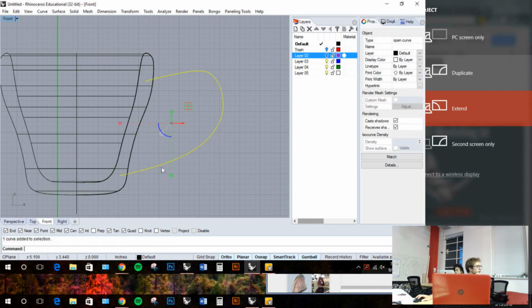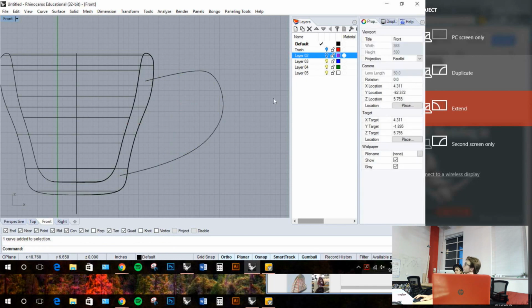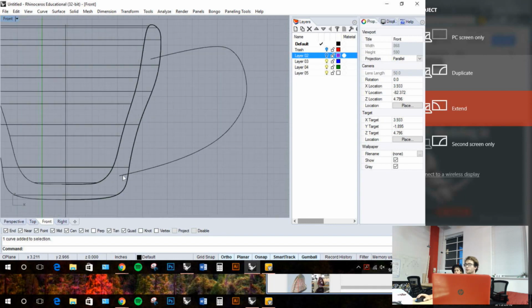Is anybody having trouble with that? Mine's like sticking to each of the edges. Like I can't select. Okay. If it's selecting the edges, hold Alt, or for Mac users, I believe it's hold Command, to disable the object snaps temporarily while you draw. You could also go to the object snap panel and just disable all of them for now. There's like a little disable button.